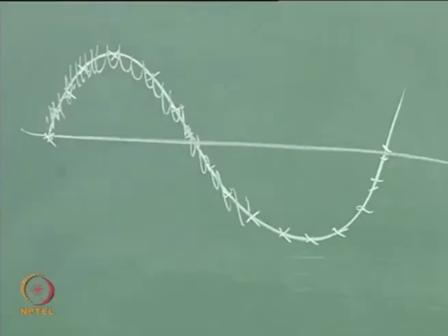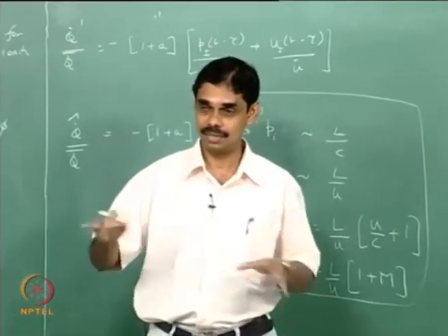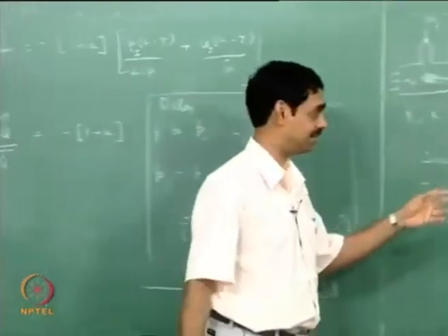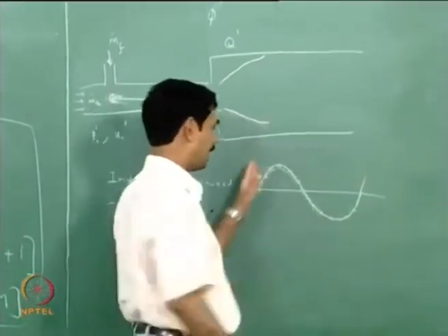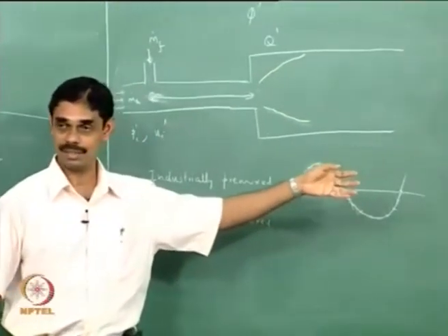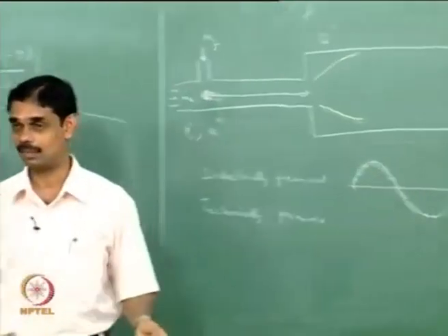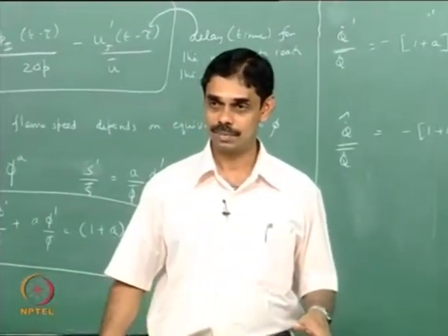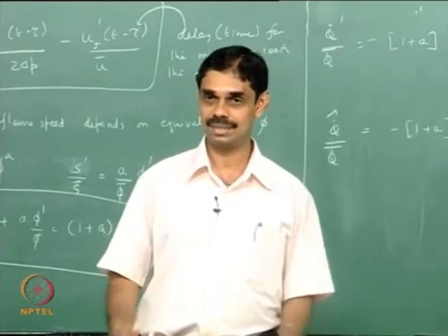So you have, let us say, a clean pressure signal, or you can even take a tube, connect a loudspeaker to this combustor and drive it with some sine wave. Let us say we phase lock the signal with that. I have seen some experiments like this, one of my friends used to do, and you would see a lot of fluctuations on top of this signal, which is phase averaged at the acoustic period. So could you call this turbulence? Perhaps, but that's difficult, because we can't quite separate under non-uniform flow and under heat release fluctuations. Hydrodynamics and acoustics are very coupled.